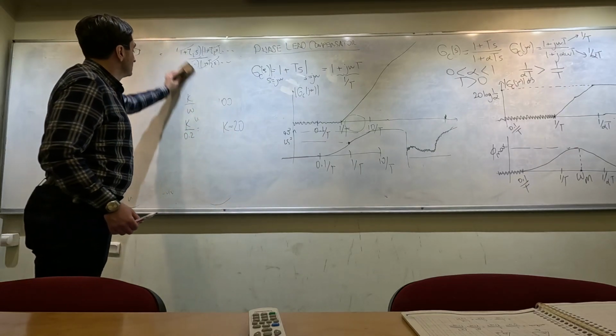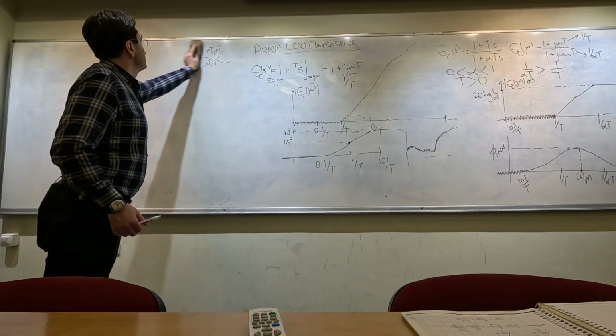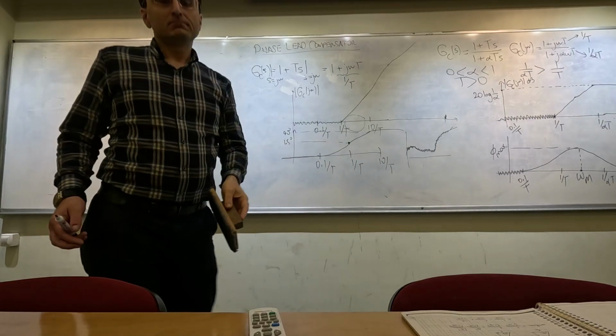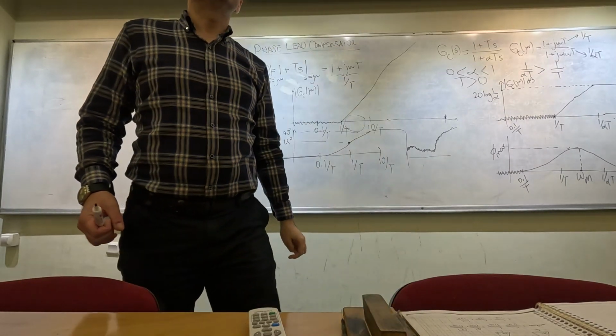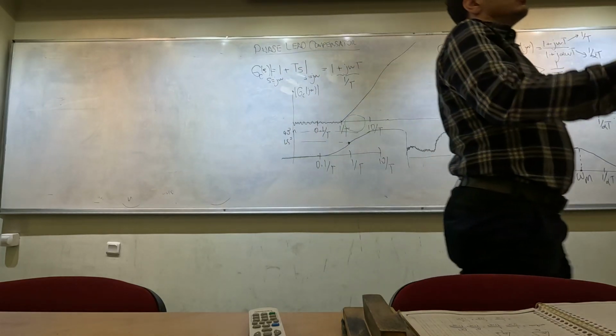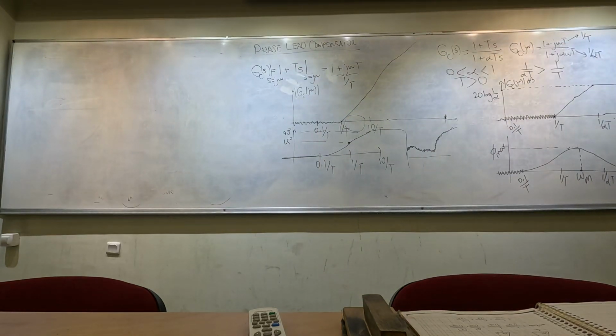Yes. You said that we can implement an integrator with passive elements. An integrator or derivative, you cannot implement from voltage to voltage or from current to current using passive elements only. So phase lead compensator is the same, right? For the phase lead compensator, you can actually implement it with passive elements. That is one of the advantages. Using only resistors, capacitors, and inductors, you can implement this thing. So without actually spending any power, you can implement your controller.